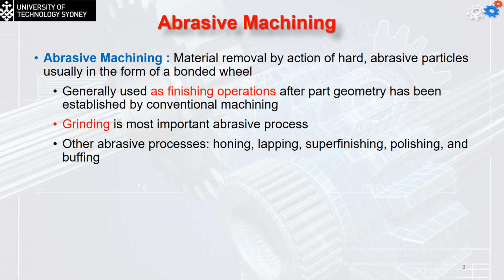That means we are going to require a little bit of machining on it to have the accurate shape. The disadvantage of this process was too much energy to melt the material and shape it once again. And also we are going to have inaccuracy with the size due to the expansion and contraction of the material.